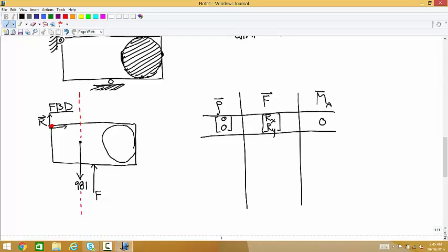What's the rho vector from the about point to where that weight force is applied? Yeah, you'd have to sort of recalculate, but we do know it has the same x position, and we don't care about the y position, so I'm just going to put this in as 0.680.